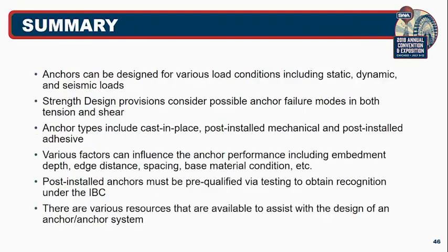So, summary. Anchors can be designed for various loading conditions, including static, dynamic, and seismic loads. Strength design provisions evaluate all the possible failure modes for both tension and shear for different anchor systems. Then the different types of anchors include cast-in-place anchors, adhesive anchors, and mechanical anchors.